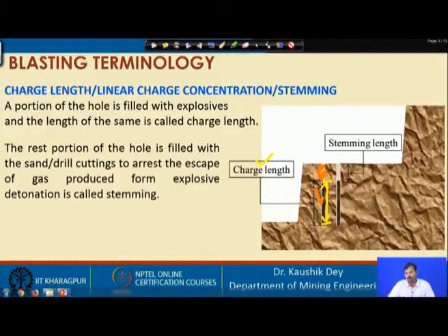That is why the gas pressure can be utilized for throwing the fragmented rock. So we insert explosive up to a certain length, which is called charge length. The rest of the drilled hole is filled with some inert, non-reactive material to close the mouth of the hole, and that is called stemming length.